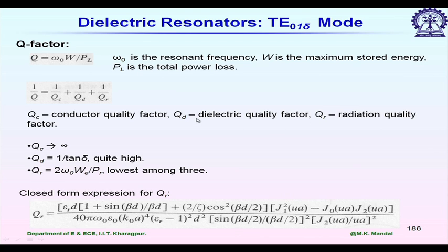If we want to use the dielectric resonator in filter application, this overall quality factor should be as high as possible, so that we can say that the loss inside the structure is minimum, and it stores almost all of the given energy inside the structure.